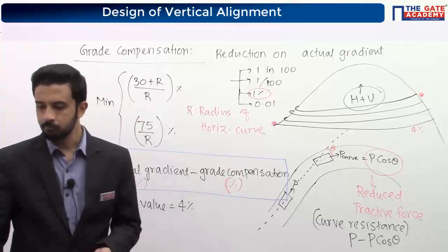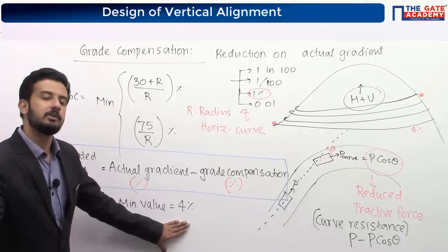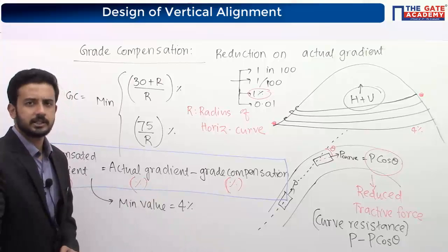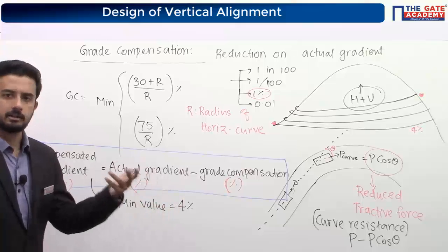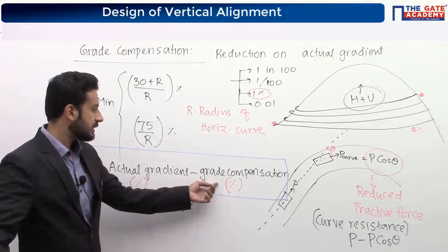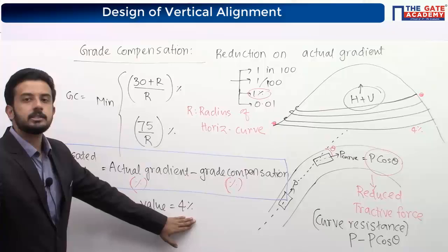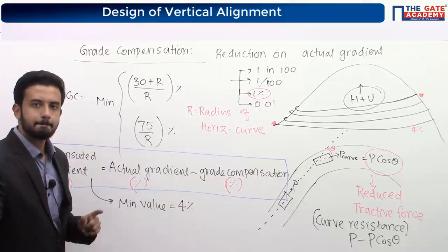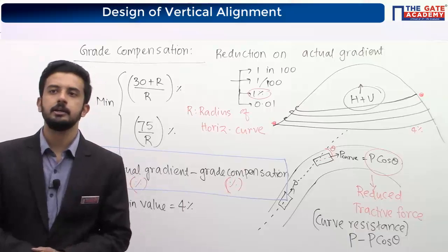That's why, in some questions, this rule will come. Okay, we'll see how to do it. Exactly in superelevation also we did the same thing. Whenever we were exceeding the limit, we were taking the final answer as 7%. Like that, after minusing, if you are going less than 4%, you have to set it as 4% only. Understood the concept? Can you do the first question then?